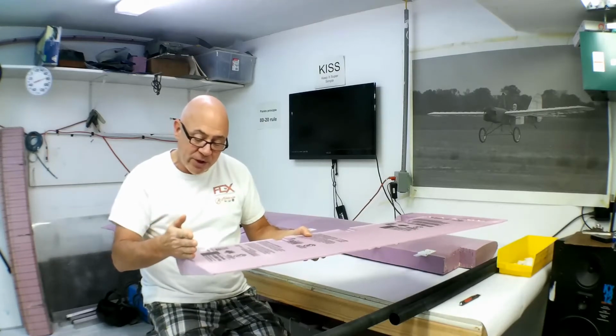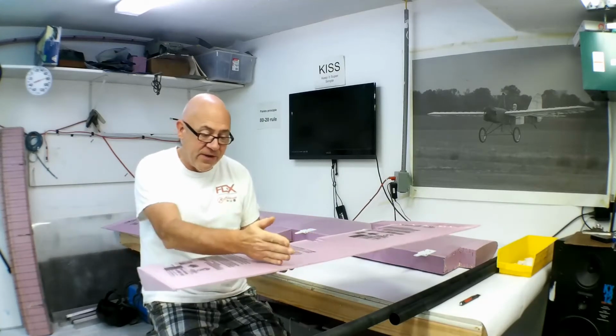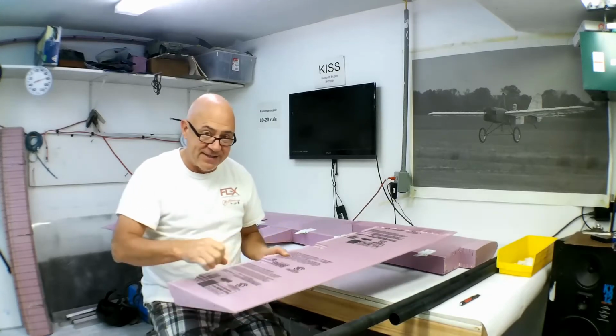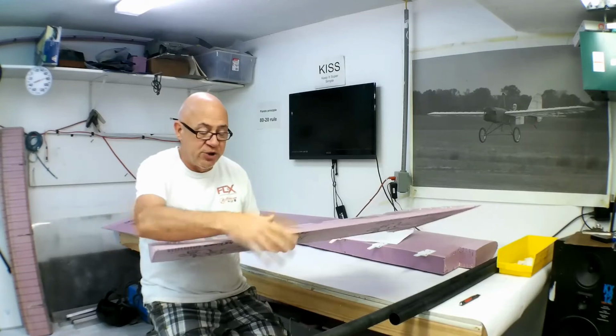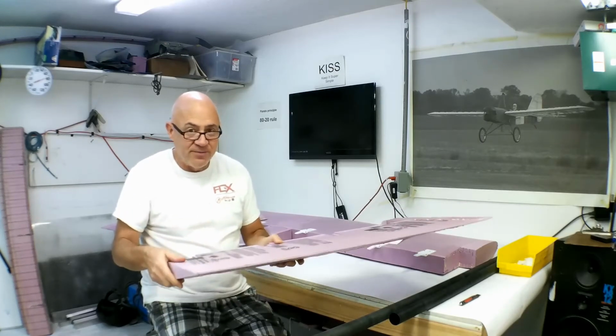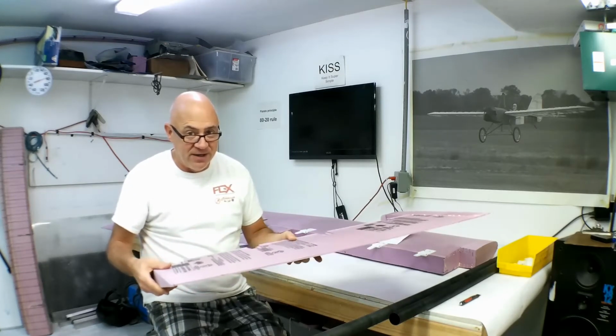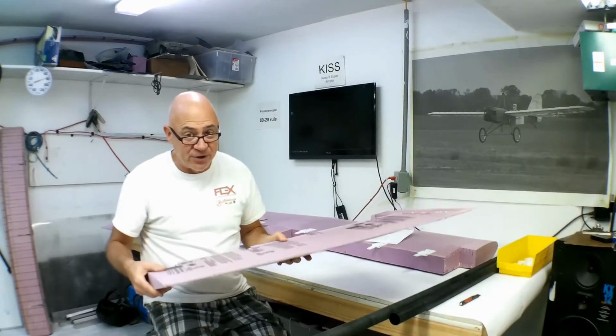But this wooden rib here and this wooden rib is epoxied to that socket. And then the ribs are epoxied into the foam, and once you sheet all of that, those two ribs are supporting almost all the load that goes into the wing and the sheeting of that wing. So there you get your strength.